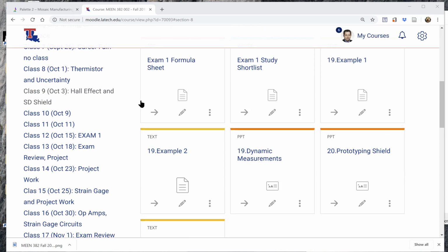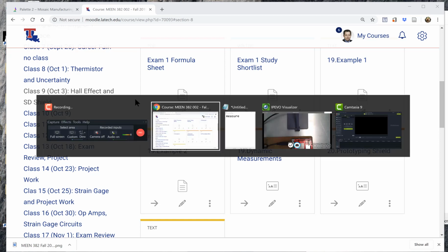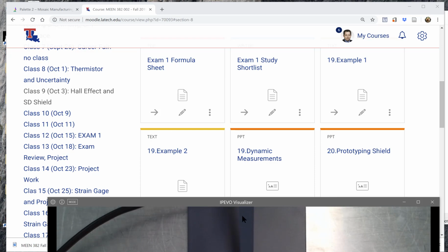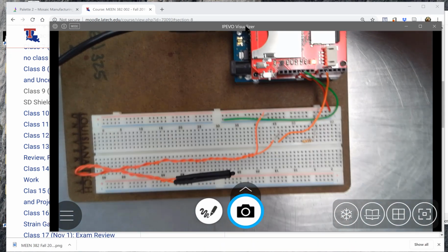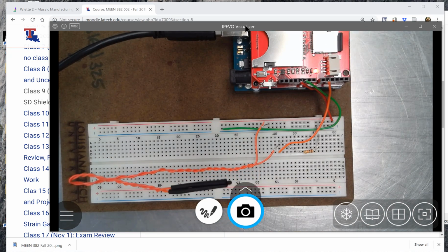But what we're going to talk about is a little bit on, I have got my thermistor hooked up. We actually did this last time where we had the thermistor here, and mine is not sealed. I still never went back and sealed it. So if you have not sealed yours up to where it can be inserted into liquid water, then you do need to seal this end up, because the way you're going to calibrate yours is with water. So measuring the temperature of water.